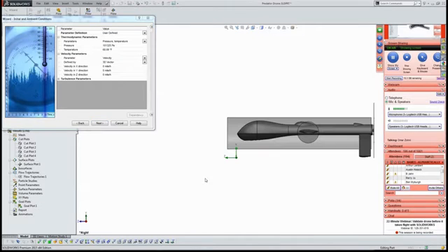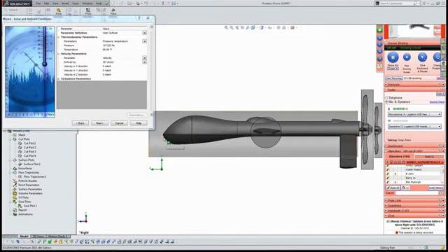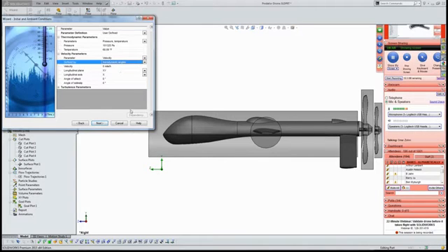But one of the most important things for an external flow analysis is that it wants us to specify the velocity, basically the wind speed. So the way I like to do this is, instead of doing a vector, I'll go to an aerodynamic angle. The plane that I want to work in is the ZY plane, so I'm just going to switch to my ZY plane. The direction that I want to be longitudinal is the Z-axis. Let's say I want an angle of attack of 10 degrees, and I want a wind speed of -100.